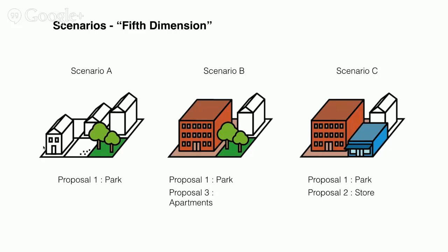And this is the fundamental construct for looking at options in UrbanCanvas: proposals are the atomic units, and scenarios are the way that they're combined together. And then for the scenario, when you're doing an UrbanSim simulation and you want to use this mechanism to specify scheduled development events, a scenario is basically the encompassing element that lets you choose which proposals are used in your simulation.